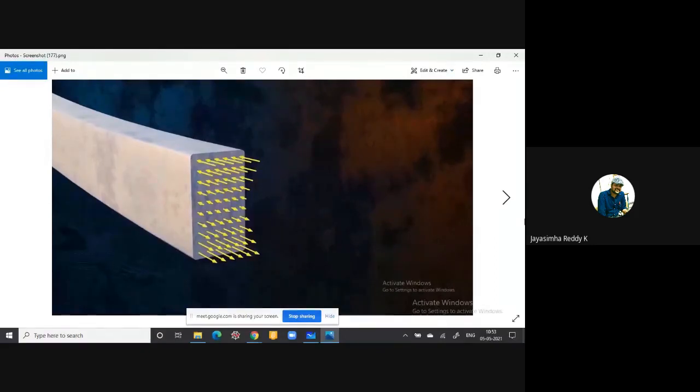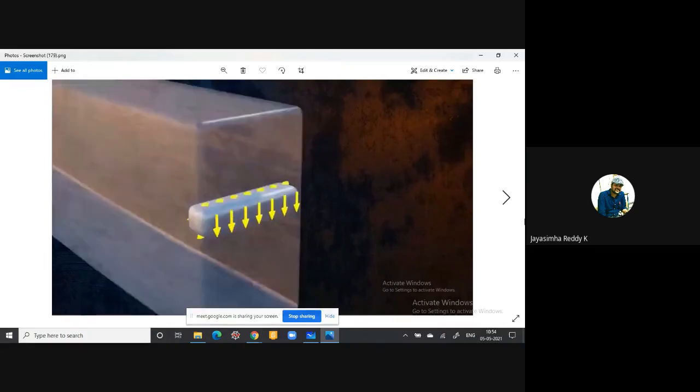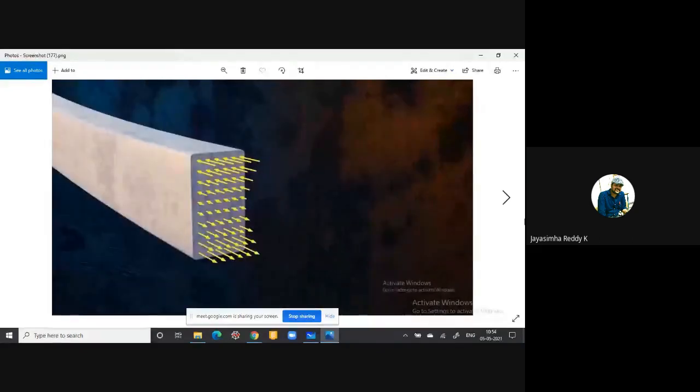And these longitudinal forces, if you observe the arrow marks carefully, the top arrow marks are tending to compress and the bottom arrow marks are tending to elongate. We have already seen why this happens. Because of this change of direction of the longitudinal forces, we have converted this change of direction into a moment, and we have taken it as a bending moment. If we join these two, we get the bending moment. Okay, is it clear, students?